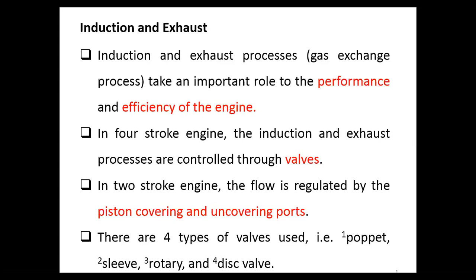The scavenging process or the exchange process plays a very important role, especially for the 2-stroke engine, in which we don't have a distinct intake process or a distinct exhaust process.